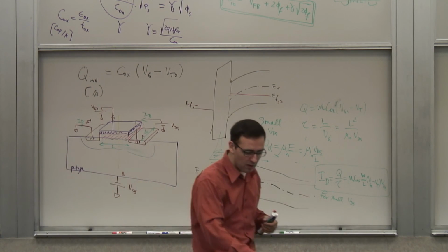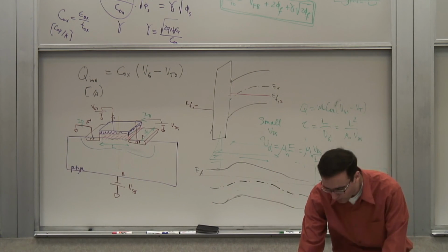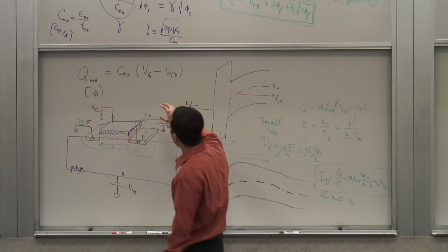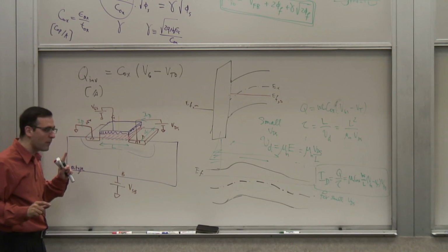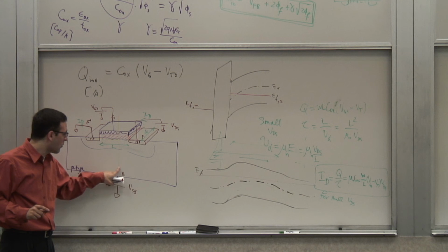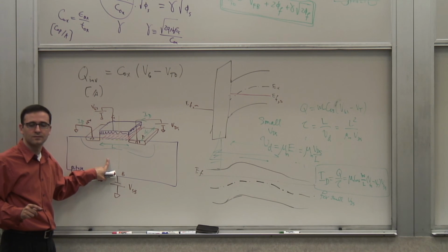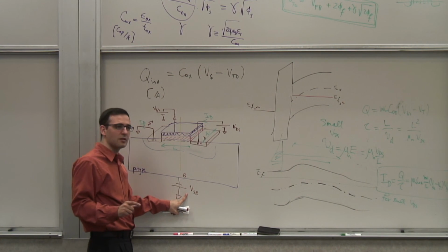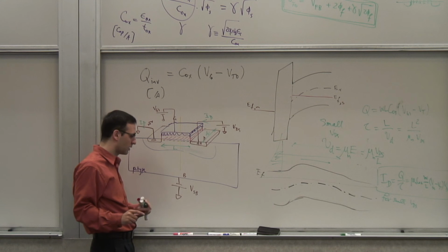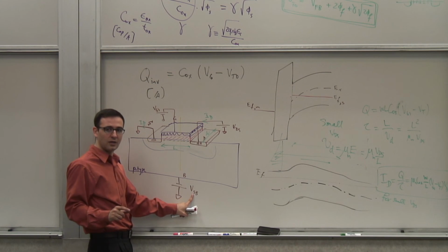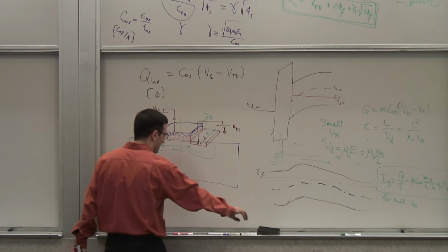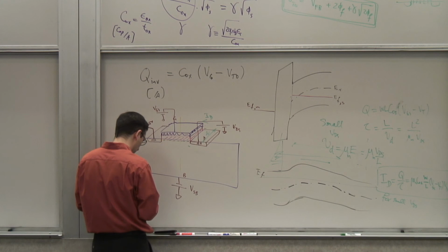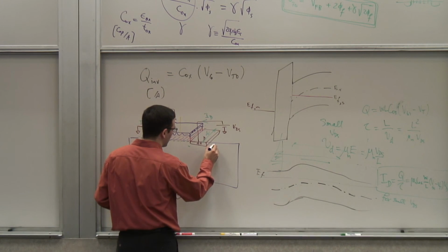Okay? Now, there's one thing before we go forward that I need to talk about, and that's basically what this threshold voltage is. So I said this is the first-order picture, but now I have to take one more thing into account: the fact that I have this fourth terminal. Think about it. If this voltage, the voltage between source and bulk, VSB, were non-zero, what would it do to my device? What would it change? Look at the transistor and tell me, what will it do?